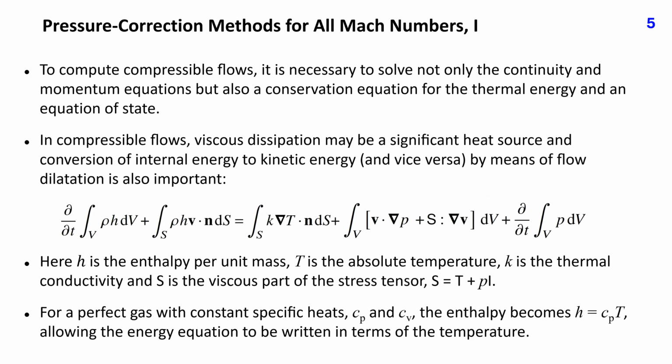To compute compressible flows, it is necessary to solve not only the continuity and momentum equations, but also a conservation equation for the thermal energy and an equation of state. In compressible flows, viscous dissipation may be a significant heat source, and conversion of internal energy to kinetic energy, and vice versa, by means of flow dilatation is also important.